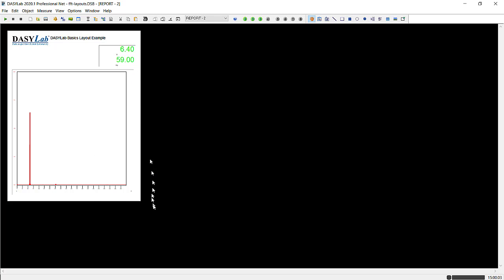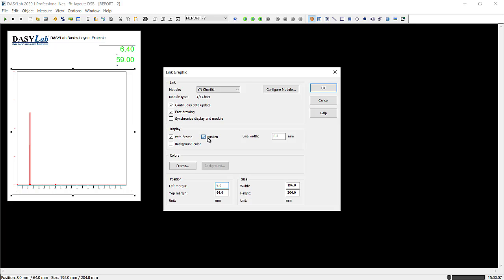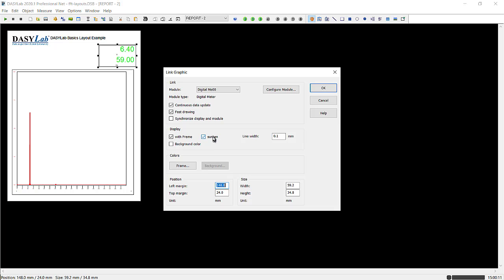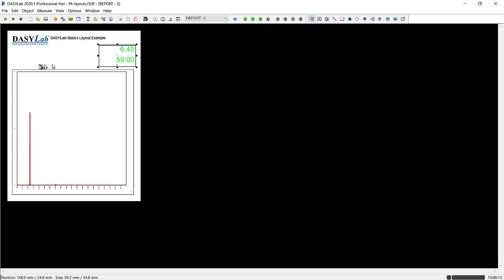The frame with the drop shadow doesn't look quite right, so I'm going to turn off the drop shadow and just leave a straight frame. So I'm double clicking on these objects to be able to open them up. You can add any more text information that you want on here, and we'll talk some more about that. And I need to go back now to the worksheet view. This time I'm going to use the shortcut button on the function bar.